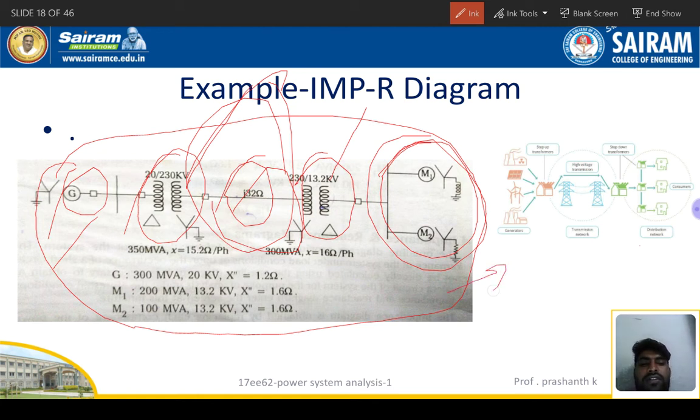So the corollary of this is this one. See, there are power plants: thermal, solar, wind, or nuclear, or whatever. It's a generating station, so a generator must be there. Just keep it in your mind. The generator is a synchronous generator; we use non-salient pole turbo generators for thermal and nuclear power plants, and for hydel power plants we use salient pole synchronous generators.